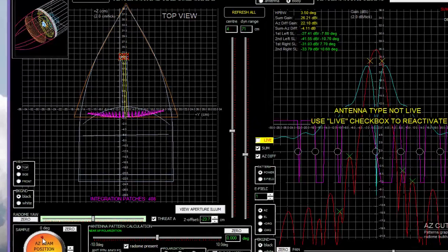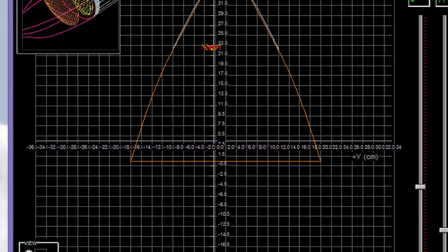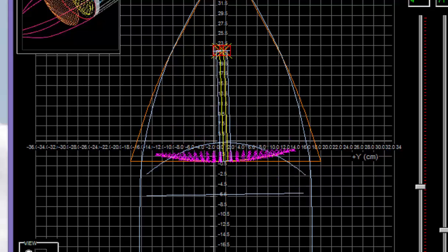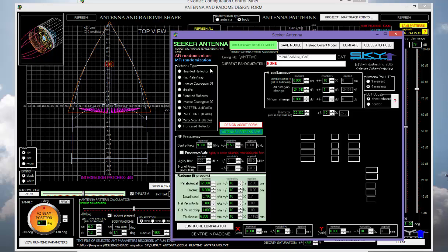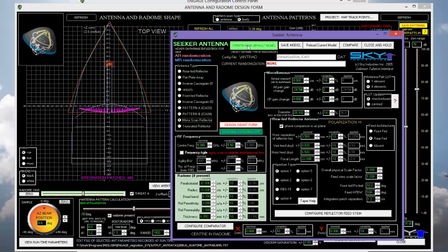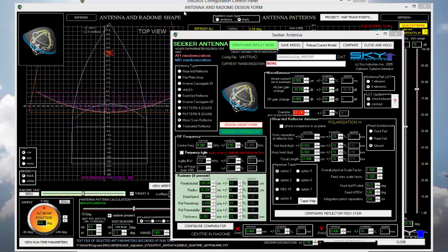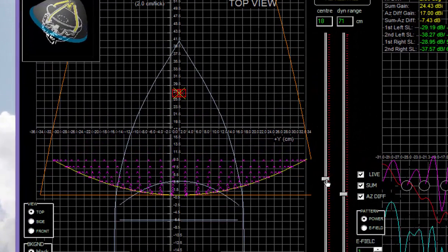And as we scan the beam, the twist mirror moves at half the rate of the reflector. Now we can see something interesting if we change the antenna model from a reflector type to a mirror scan antenna. So select that, click Create and Save Default. Now this antenna is a mirror scan antenna. It's a little bit bigger than the last one, but we want to see it up close anyway, so we'll just change the offset a little bit.